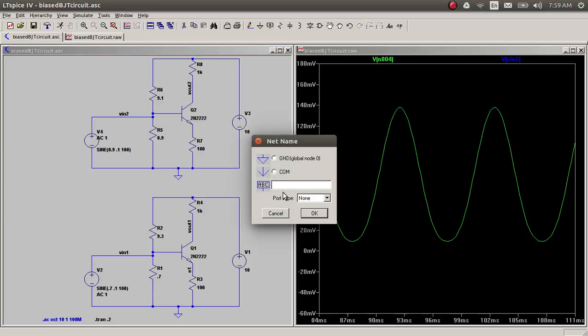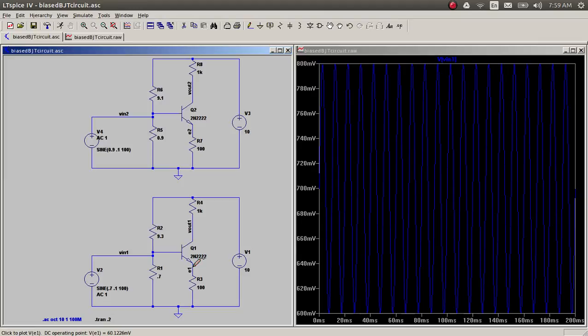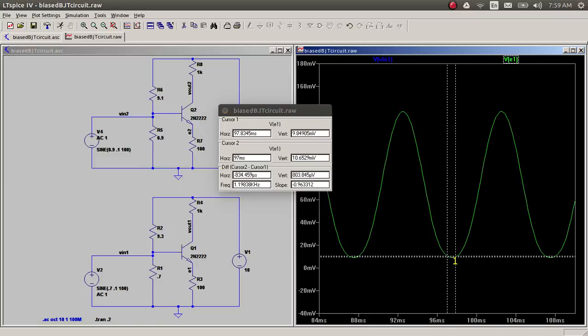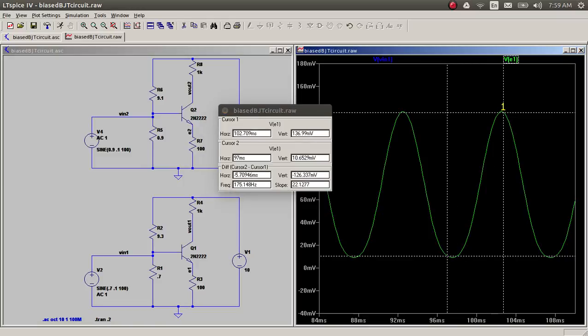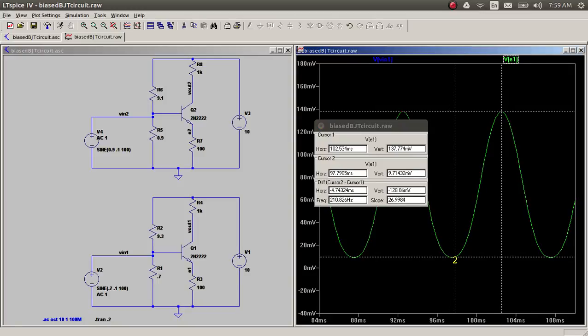and emitter 2. So just run the sim again. One at the bottom and one at the top, and the difference here is 127 millivolts, so approximately 63 millivolt difference. Sorry, maybe a little more than that, 64 millivolt is all we are getting. Although we are feeding 100 millivolt at VN, we are only getting 60 millivolt at the output.